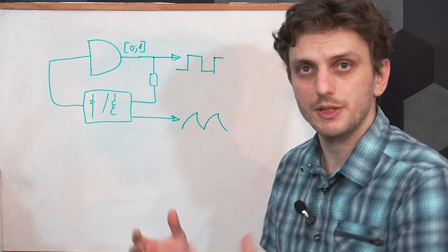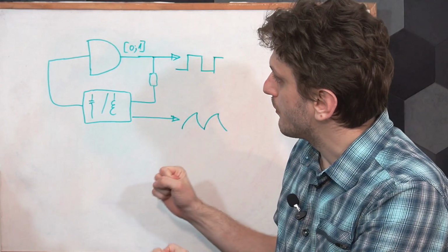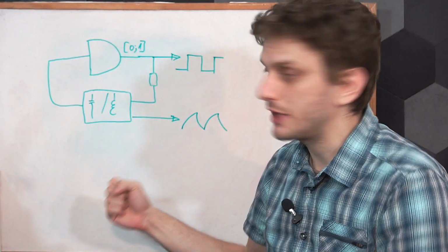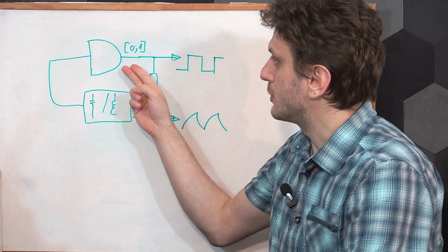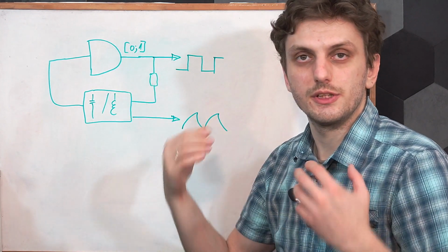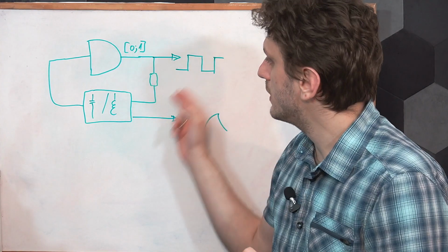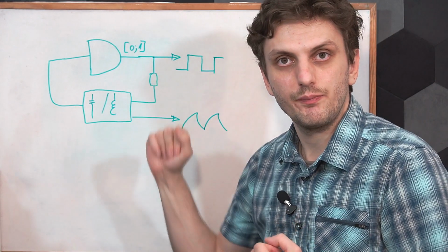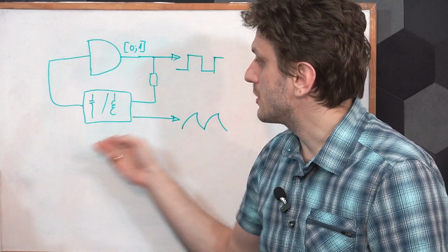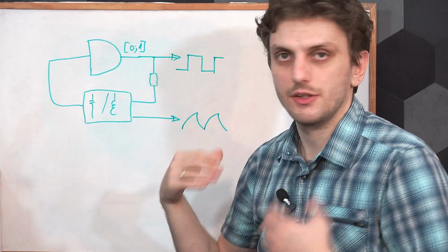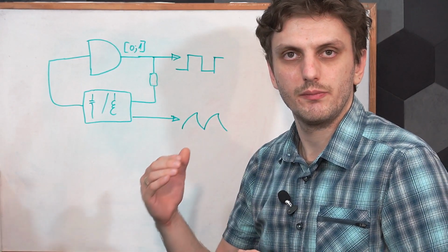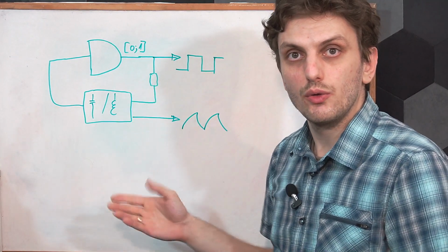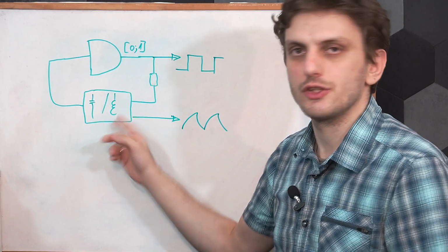To see how this works, I prepared this block diagram. We still have a signal loop, but rather than having an analog amplifier, we have a digital amplifier, which can output two digital states, a 0 logic and a 1 logic. Then this gets passed into a storage element, which charges and discharges based on this output value, and then based on the voltage on this element, the circuit switches. So we can get our square wave output if we look directly at the output of the amplifier, or we can get a triangle wave if we look at the storage element.